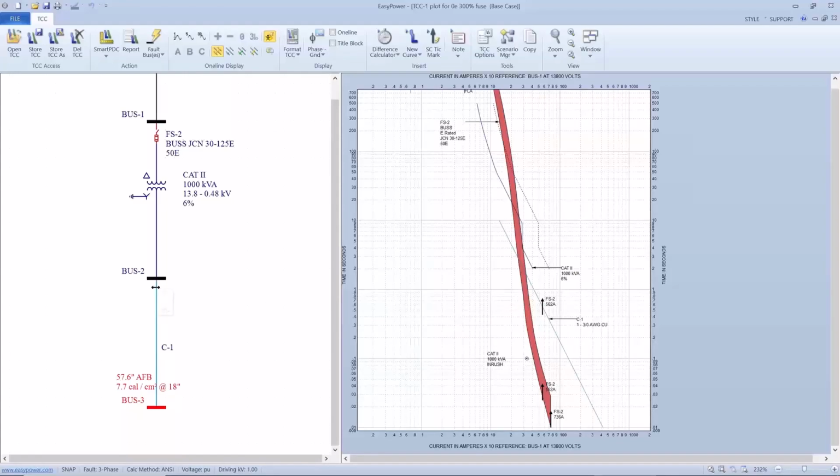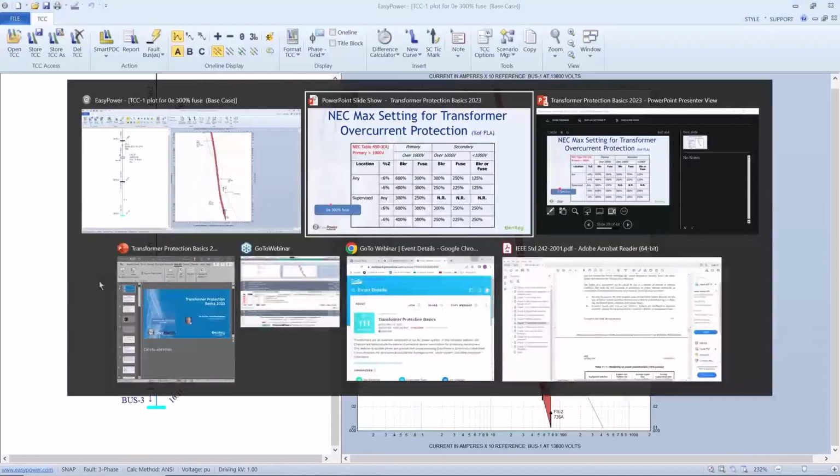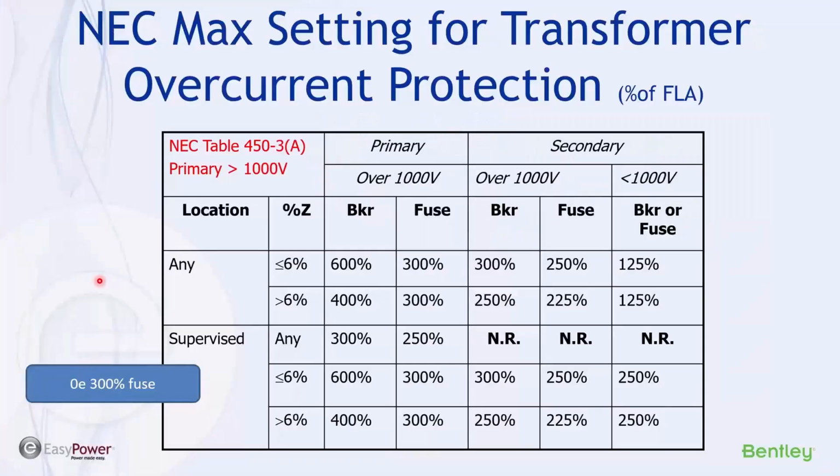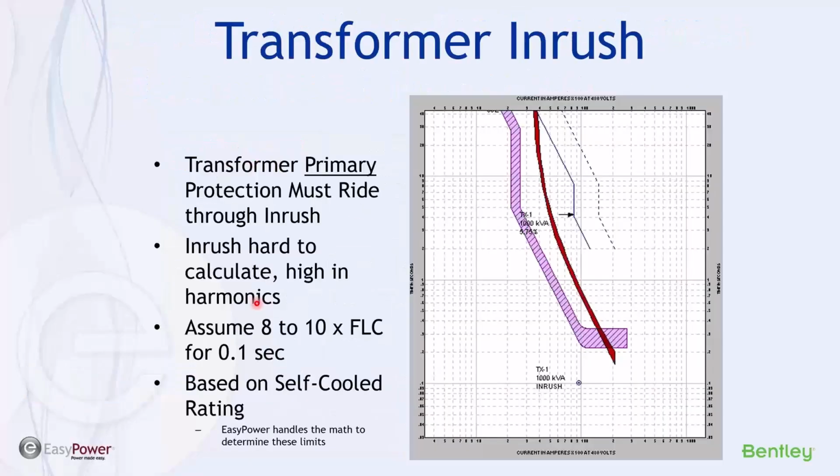Yeah. So this is just a short cable. In fact, in my Paradox example, this is limiting to 16,000 amps, so that's pretty high, and it's potentially going to exceed the damage on the cable itself. So this table should not really be considered for arc flash protection. This is strictly the restrictions for transformer protection, and it may not be adequate to do coordination downstream. Okay, so much for that.